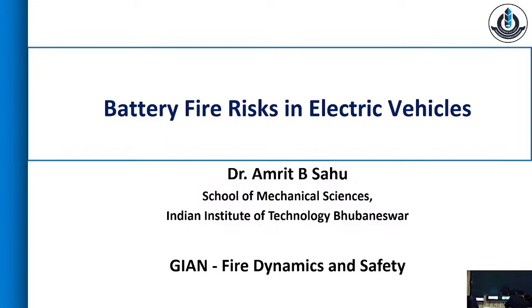Okay, good morning all. Last class we basically looked into something related to chemical kinetics, and how it is associated with heat release rate, and how it plugs into the species conservation equations and energy conservation equations. So the rate at which a reaction takes place in a combustion zone is going to dictate the net heat release rate that is happening during the process. That was all based on gas phase reactions.